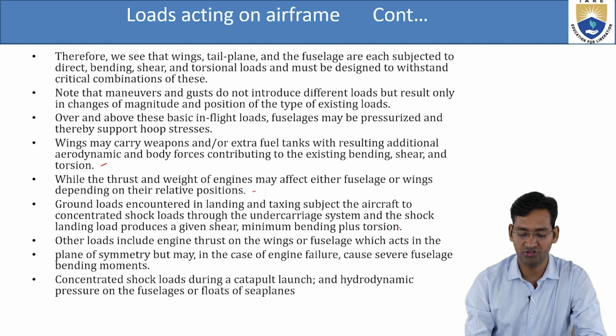Other loads include engine thrust on the wings or fuselage, which act in the plane of symmetry, but in the case of engine failure cause severe fuselage bending moment.